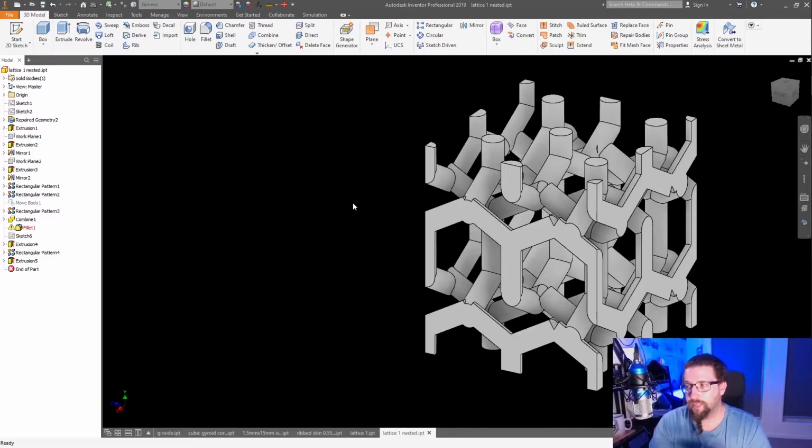But again, this is going to be quite heavy because of the way that it has to distribute to the entire volume of the inside of the thing. And say that this lattice structure constitutes a 60 to 70% remaining volume of the original volume of the wing. That's still leaving 30 to 40% of the mass that you still want to get rid of. You want to try and bring that down to about 95% mass reduction, not 30 or 60.